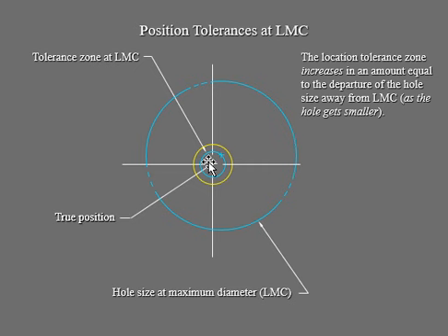Again, you're not dealing with the diameter of the hole, you're dealing with the position tolerance of that. So don't go fast, go very, very slowly, to be able to understand what it is that you're looking at. I think students usually look at the diameter instead of the position of where that hole is going to be on that part. Where it is on the part is not equal to the dimension of its diameter. We're dealing with the location, position.